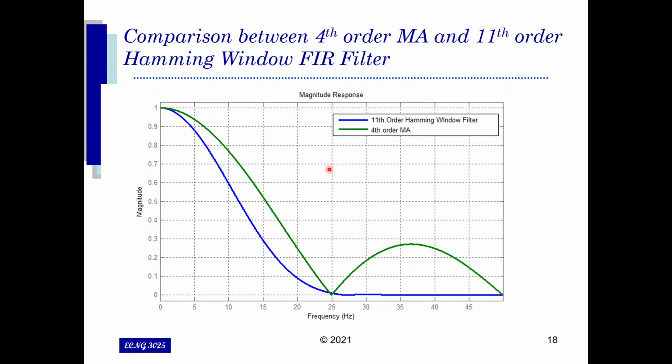And for the moving average, we saw all you need to do is just calculate n, which is going to be fc divided by fs. And for the FIR filter design using the Hamming window, we just need to start with the ideal low-pass filter response. We calculate our vector values for h of n. Then we calculate our vector values for w of n. The windowing function typically is given to you. And then we just multiply the two, get the anti-causal transfer function, and then transform that into a causal transfer function by just applying the delays accordingly. That basically will be the end of the question at that point.